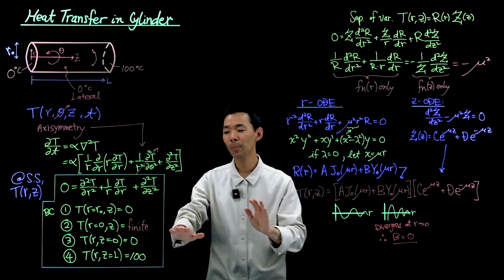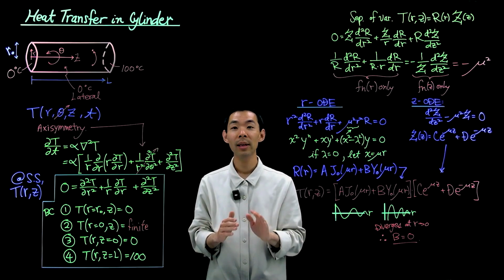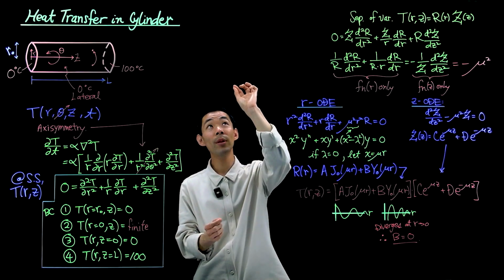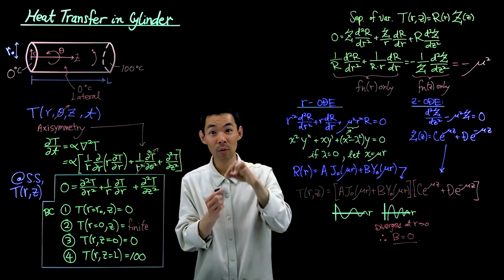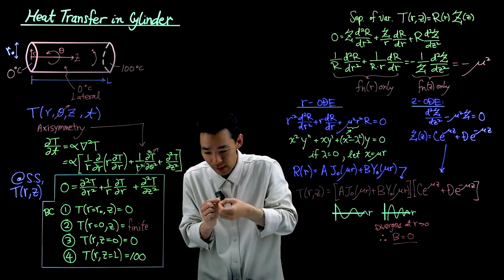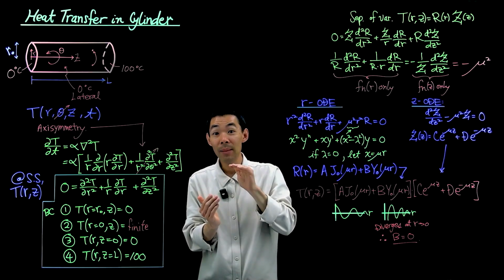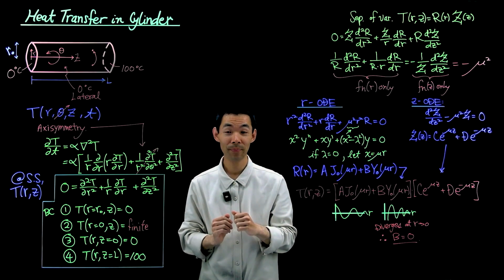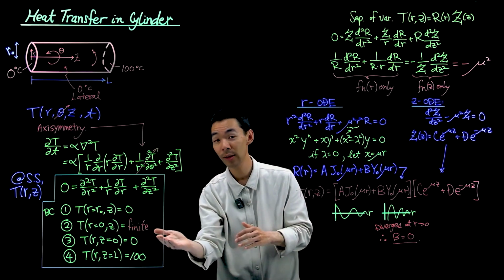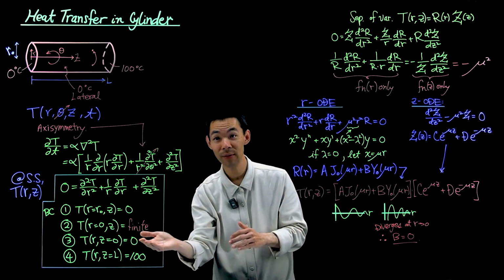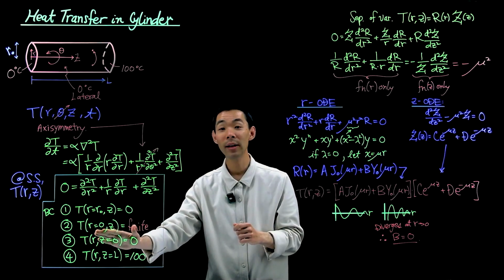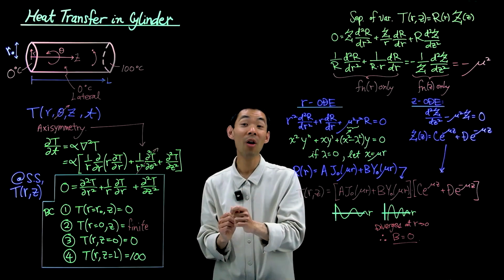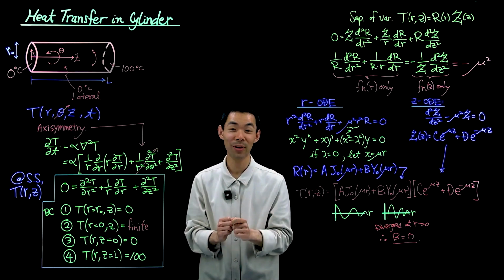Another way to pose this boundary condition is what's called a symmetry boundary condition. It's saying that as I go from the North Pole to the South Pole and cross the origin, the derivative must be equal to 0, meaning that it must be symmetric without a weird kink happening at the origin. So sometimes you'll see this boundary condition written as the derivative of the temperature at r equal to 0 must be equal to 0, and people will often call that a symmetry boundary condition.